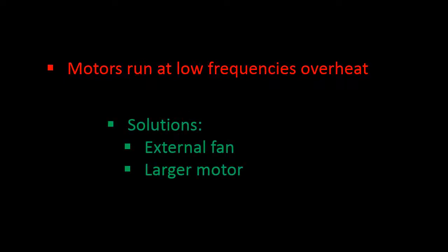Even with voltage control to avoid saturation, the motor will still tend to overheat at low frequencies. Using an external fan or upgrading to a motor of larger physical dimensions can help with this by increasing the airflow over the coils.